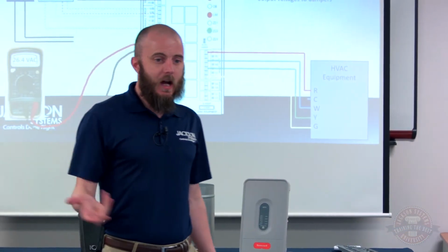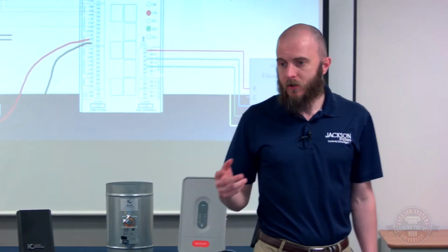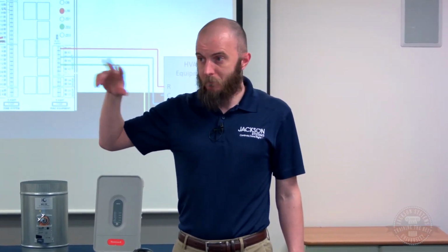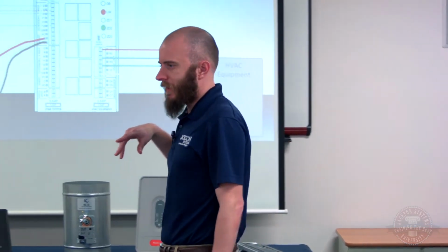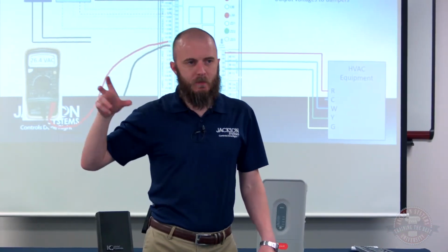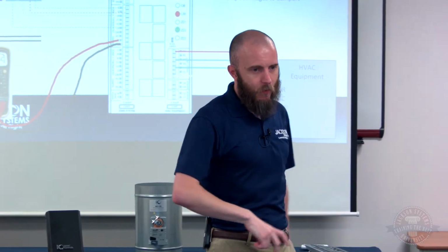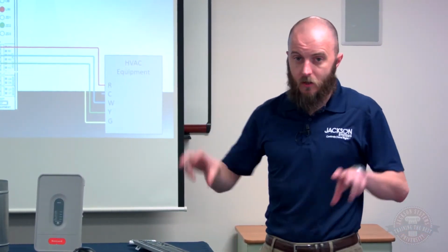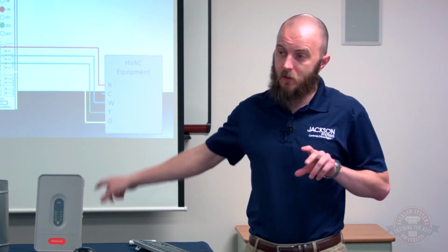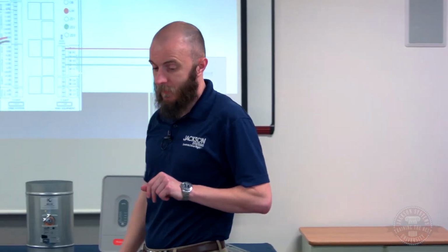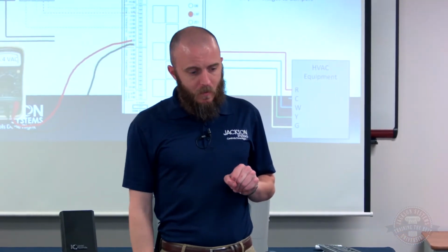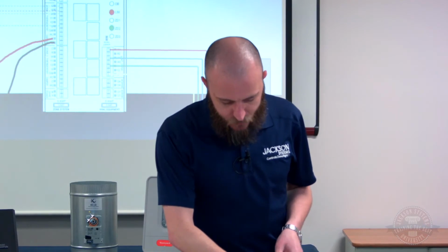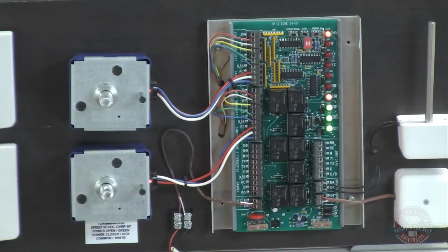The reason being, some damper actuators will actually produce a feedback voltage, and you'll see voltage on both sides, right? The one I'm most familiar with that does that is Siemens; most Siemens actuators will show that. If you wire up dissimilar actuators, say a Belimo actuator in parallel with a Siemens actuator, the Belimo will not behave properly. But it's just a phantom voltage. There's not really any current there. So we always recommend first checking your output with the damper disconnected.